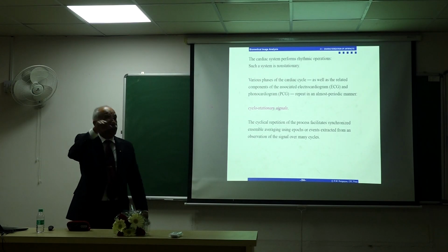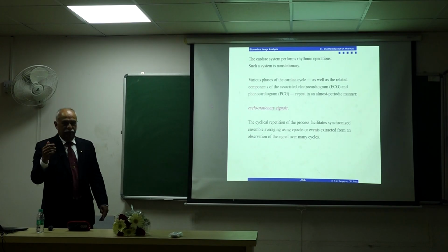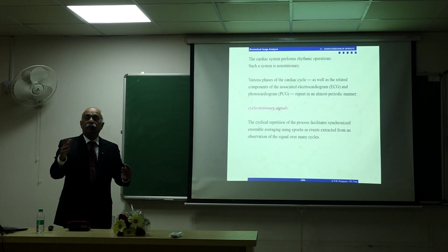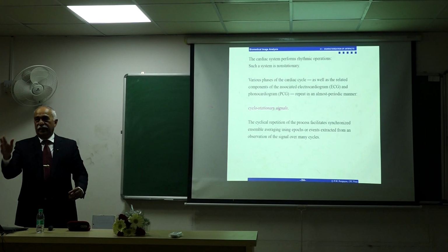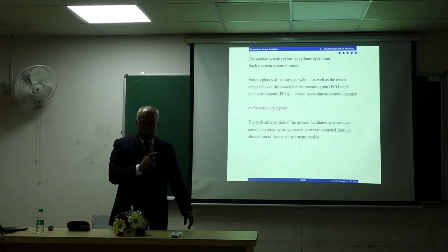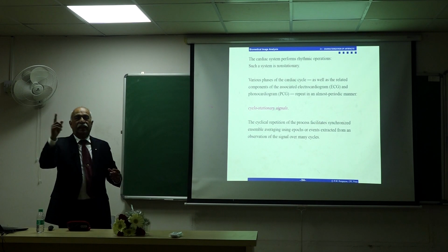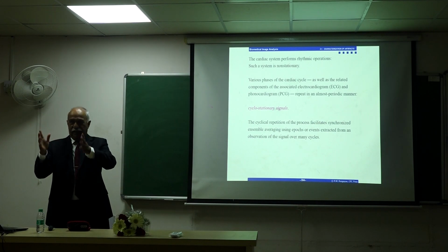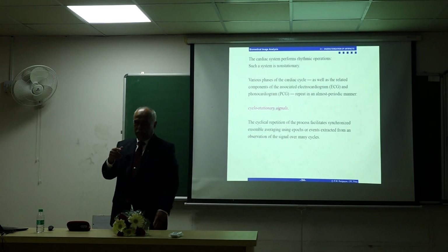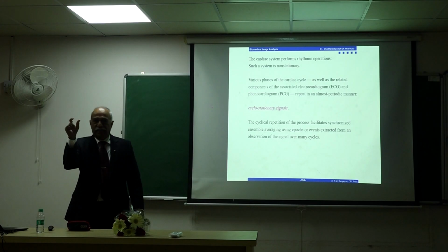Then you can average, create an ensemble of those pieces and average them, which we do in that book you saw, in biomedical signal processing, to average across multiple observations of the first heart sound only, second heart sound only, over multiple cardiac cycles using the ECG as a trigger. Or similarly, you have other applications where one signal is used as a trigger and another signal is acquired and averaged in an ensemble. So cyclostationarity helps in creating an ensemble of a signal that really is continuous, but you're breaking into parts and synchronizing them.